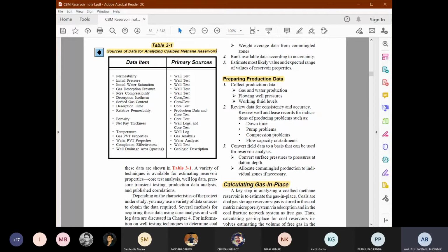But if the rock strata is so weak that there is an overlapping, that means for both the boreholes, the surrounding permeability, the surrounding discontinuities or the fractures are going to extend beyond 50 meter, then obviously the activity in one borehole is going to affect the activity in the other borehole also. So the stresses will be changing due to the activity of only one borehole. So then two boreholes will be in the near field region. So then the situation may be much more complex.